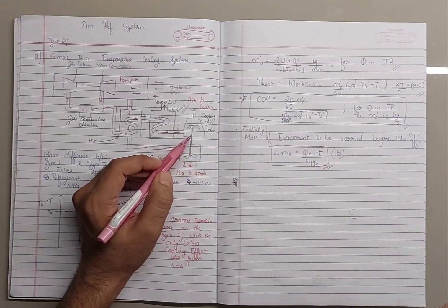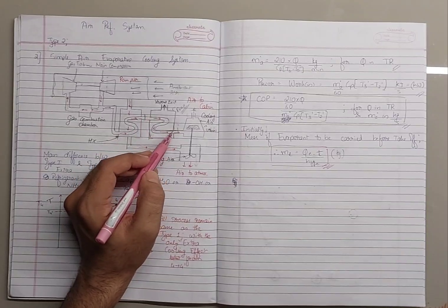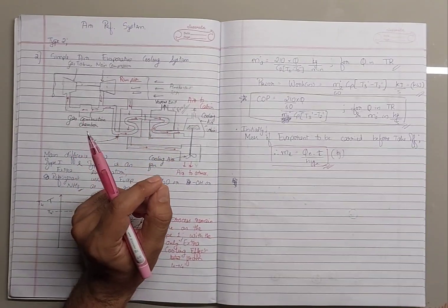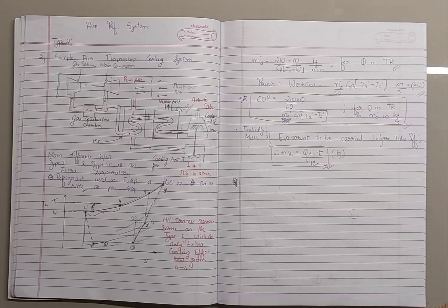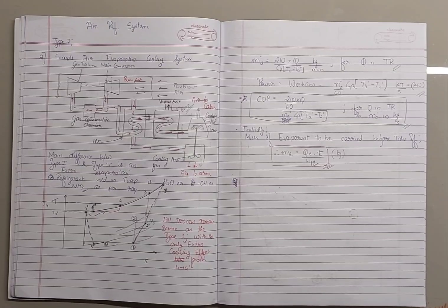There are some considerations to be made: the air leaving the system has to be expanded to the cabin pressure, and also the temperature of the air that is made to outlet from the refrigeration system should not be so cold compared to the cabin air. For example, on average, the cabin temperature of any aircraft is somewhere around 22 degrees Celsius, and if the air coming out from the refrigeration system is somewhere around 15 degrees Celsius, then it is very bad, because it can cause condensation, it can choke the system, and it can also cause over-chilling of the aircraft.